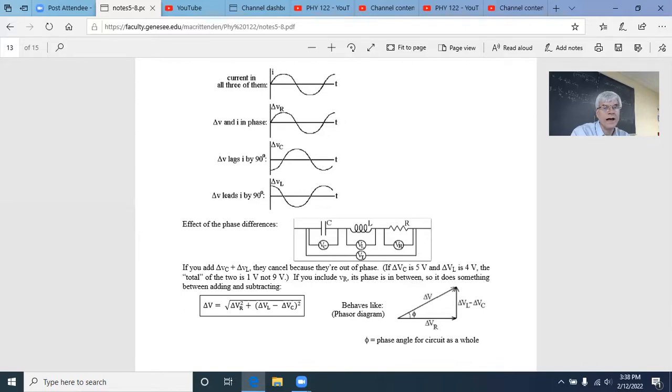Voltage doesn't really have a direction, as in over here we have 5 volts toward the north, and over here it's 3 volts toward the east, or anything like that. Voltage is just simply how much of a difference in potential is there between the one end of the resistor and the other. But see, the directions on the diagram aren't real directions like north or east. Rather, they correspond to phase. That's why it's called a phasor diagram.